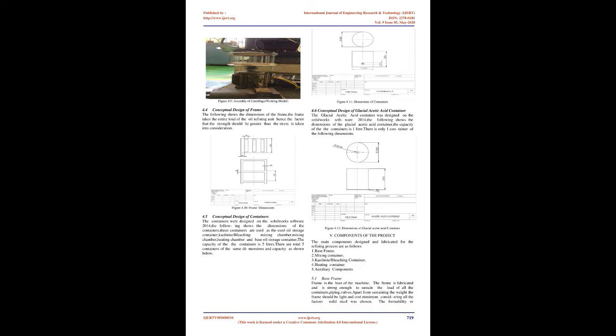2.5 Centrifugation. The mixture then undergoes centrifugation at 3000 rpm for a period of 30 minutes. Thus a black dark sludge at the bottom of the container is obtained. Followed by bleaching using activated carbon, which is done to adjust the pH of the oil to neutrality. 1.6 Bleaching using activated carbon.